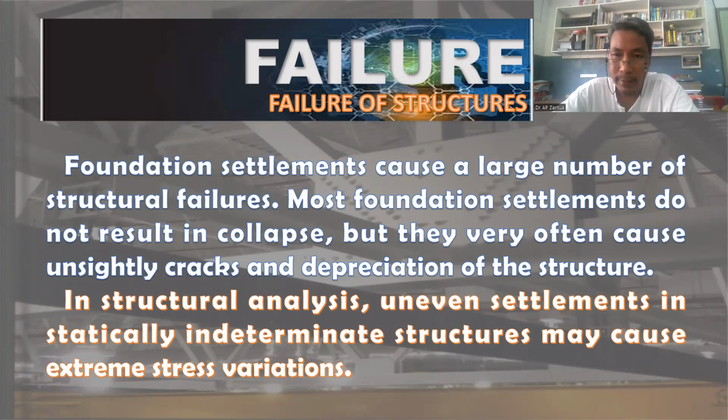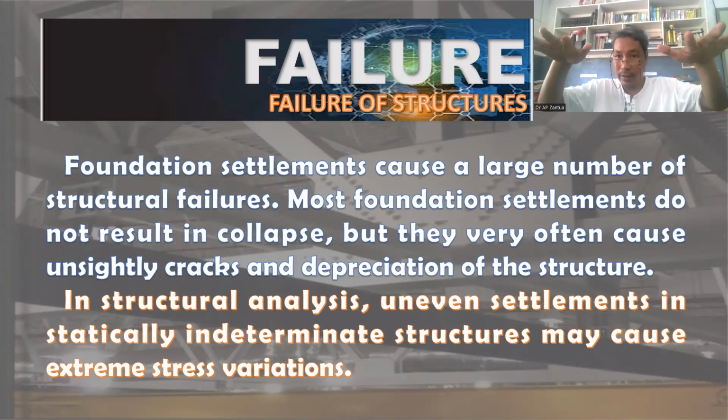And also, because of this, we have a notion that designers or engineers would like to encounter settlement that is even, or the settlement is balanced with respect to the whole building, meaning they settle at the same time, at the same pace, at the same rate.